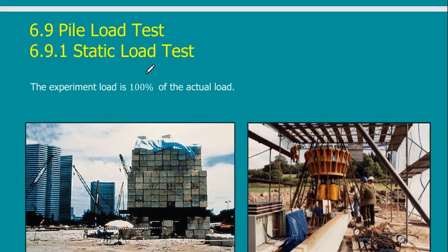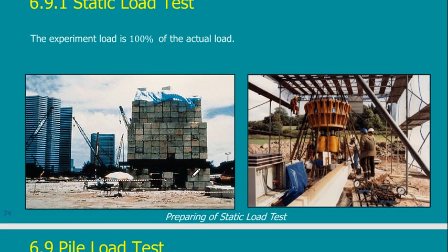Then I have the static test, or the pile load test. The pile load test is something very important because, as we said, you've seen this in the coursework. We have a lot of values when I use different methods for calculation. Which one is best? There is no method that I can say is the best or the accurate. Each one may be accurate in a special case. So in this case, I need to make a full-scale test in any project.